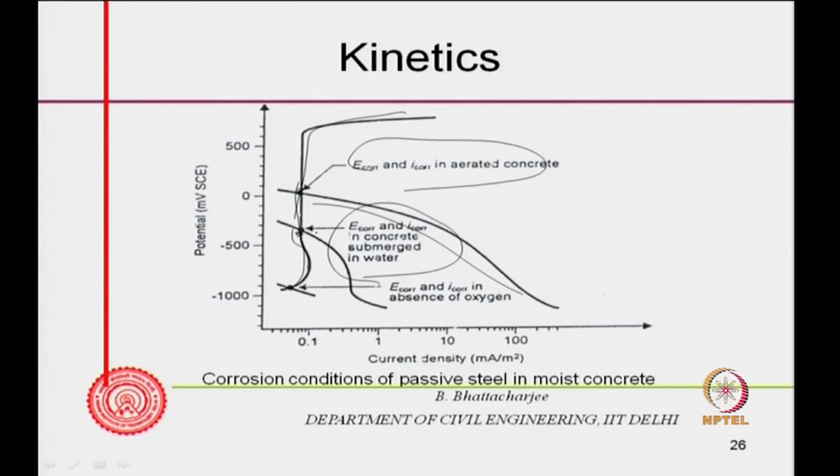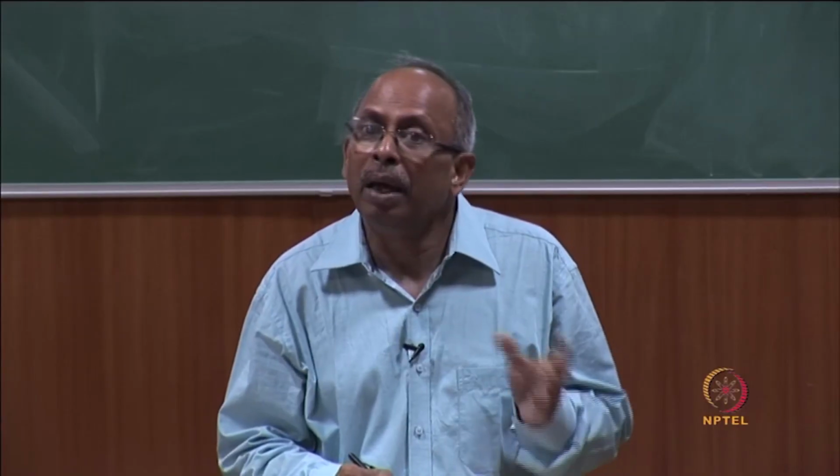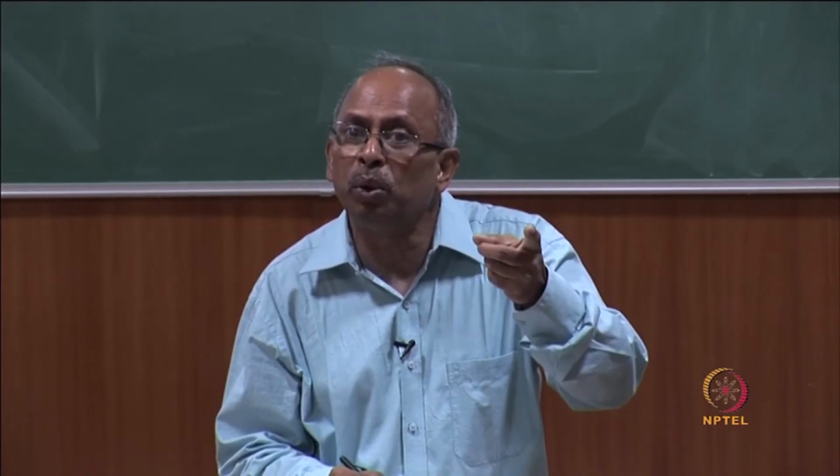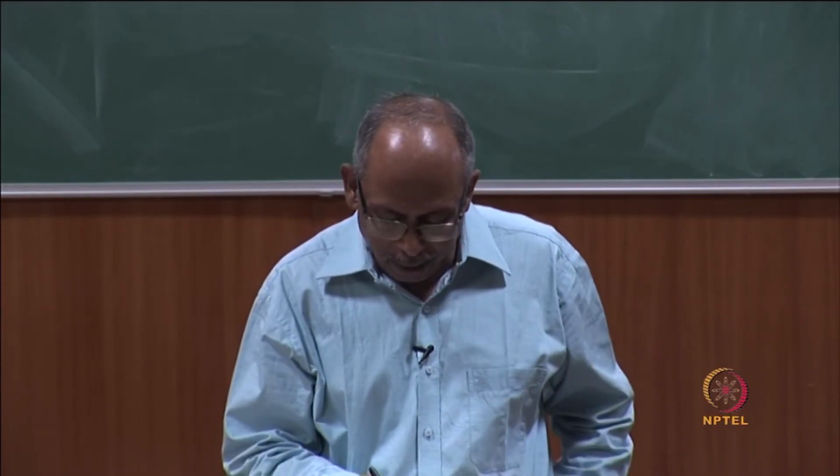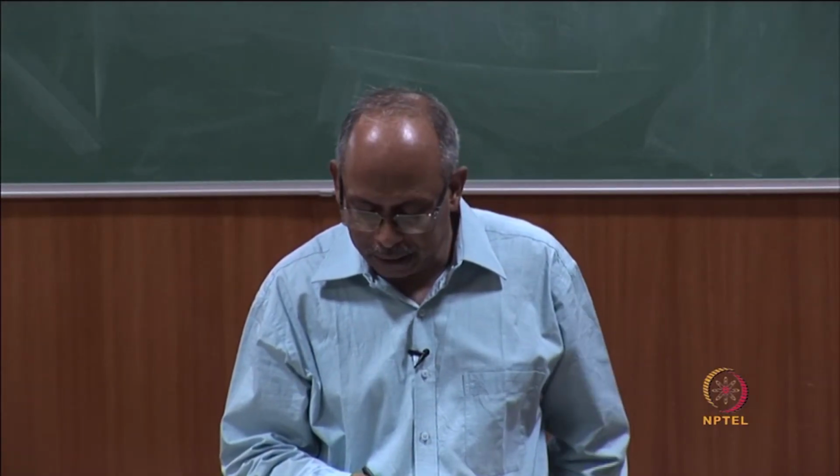So, if the corrosion rate is increasing, in some cases it might get passivated, that means oxides are formed and then it stops, but at a very high potential that might get broken down, and so on and so forth. So, the kinetic behavior of the electrode can be studied by the anodic polarization curve. One of them I showed earlier, and it can be studied by potentiostatic studies.